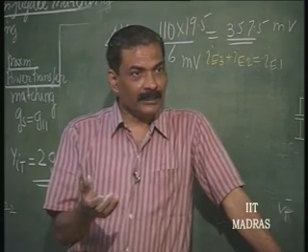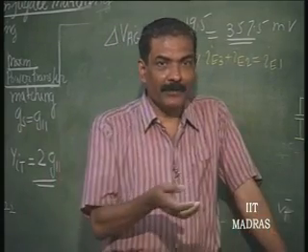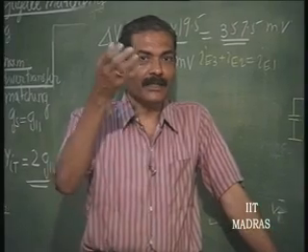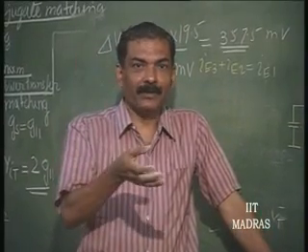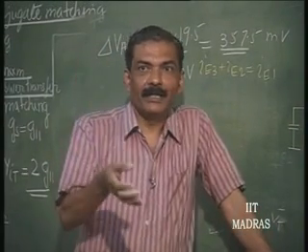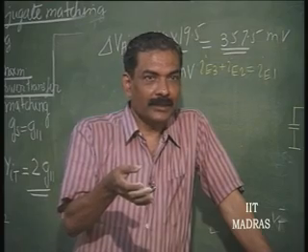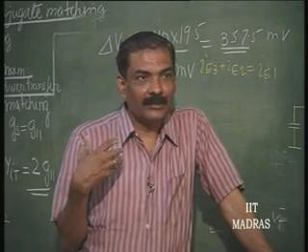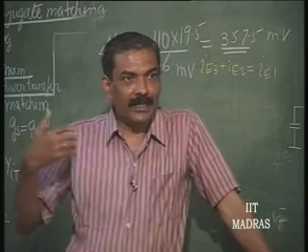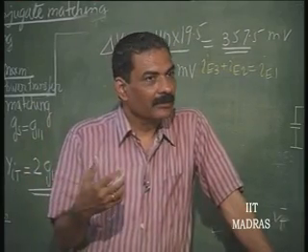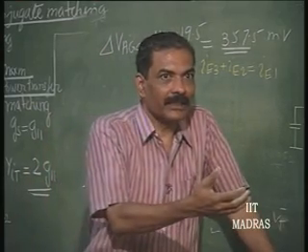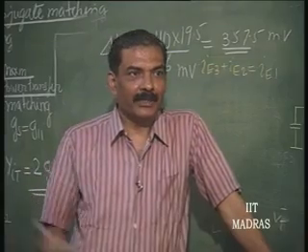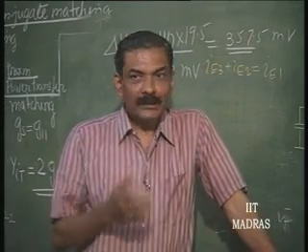If such a thing is amplified by our amplifiers, sometimes the amplified signal is too strong for the power amplifier. So, the power amplifier may get distorted, and sometimes it is too weak that you can't hear anything. So, this effect is seen as fading, right. The output you will hear very clearly, then at the next moment you may not hear. This has to be prevented.